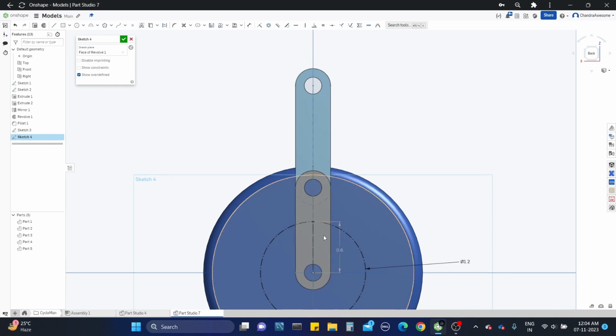Okay, so let's draw those centers. By using the transform tool, select both circles and move the positions of the circles up by 0.6. Okay, got it. Now with only two centers, the common center reaches the outside, and the other circle's center reaches this point.